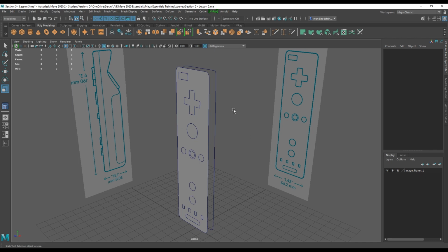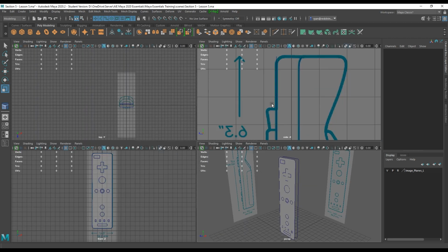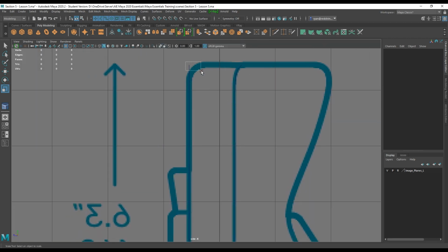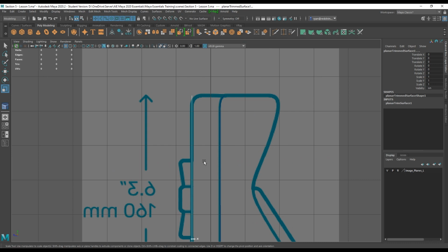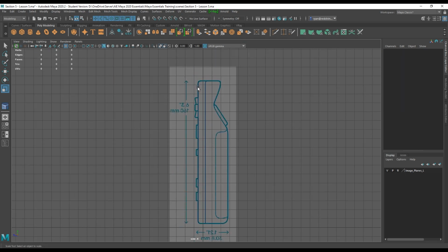And to start this lesson off, I would like to create this little round section that I see on the remote just to get some volume out of what I have currently. So I'm going to use that cool little trick we learned earlier by using multiple curves to generate a rounded corner. So I'm going to grab my curve, make sure it's the curve, and just do that. As you can see, curve.